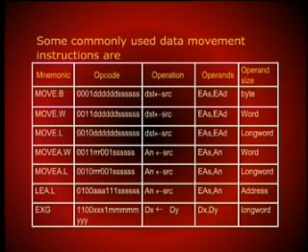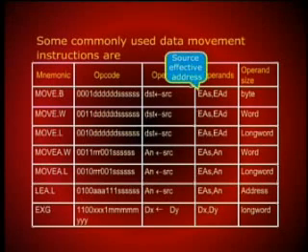move.b. The opcode in this case, which is 4 bits, is 0001. The next 6 bits indicate, in this case, the information about the destination. I hope you remember from the previous information that this data D would be available from one of the tables, and this would calculate what is called the effective address of the destination.